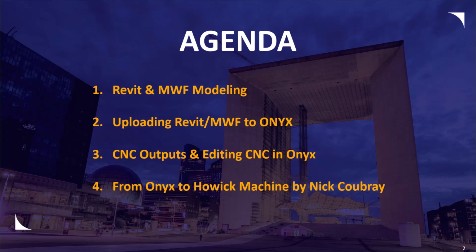Here's what we'll be covering in today's session. Revit and MWF modeling. It all starts with the Revit environment. As you may know, MWF, which stands for Metal Wood Framer, is an automated Revit-based BIM framing solution created specifically for framing your Revit model for walls, floors, ceilings, and roof trusses. Today's presentation is specifically tailored for Howick outputs. I'll be showing you some of the tools you need specifically for Howick.